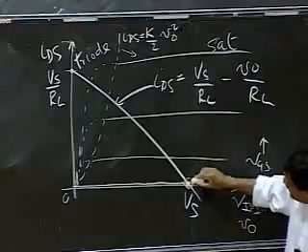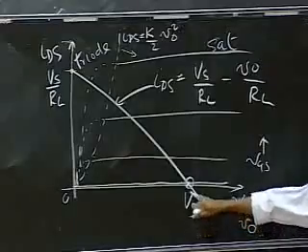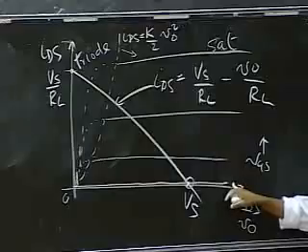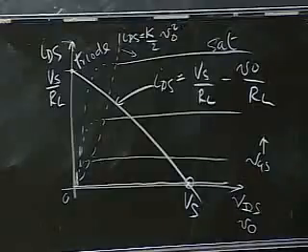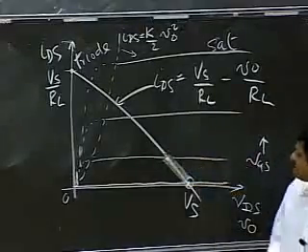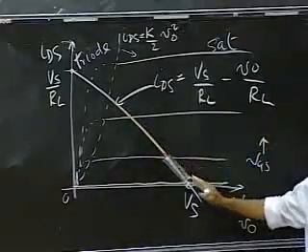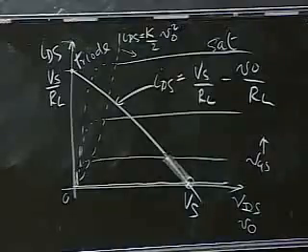So I'll start. One is this point, because at this point the output is VS, and VGS has just begun to equal VT. That's one. So think about where the second point is for valid operation. It's somewhere along that load line. Remember, the load line is a constraint that must be met by the output V naught.